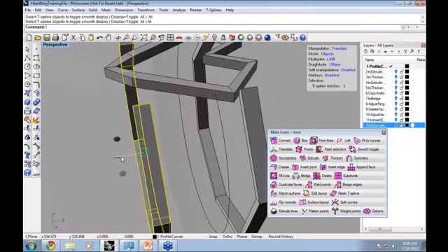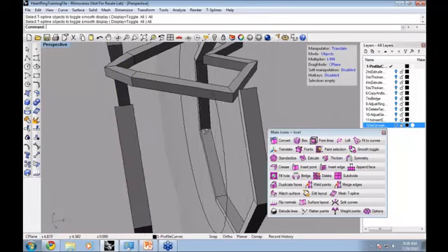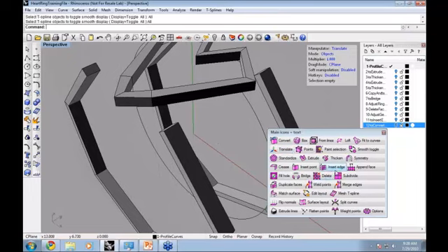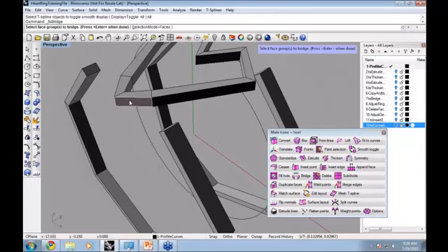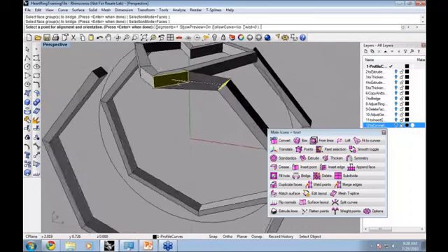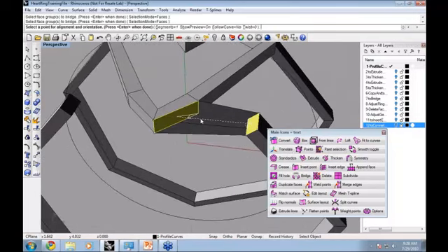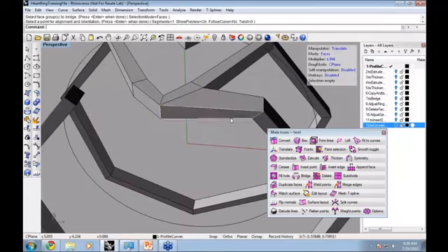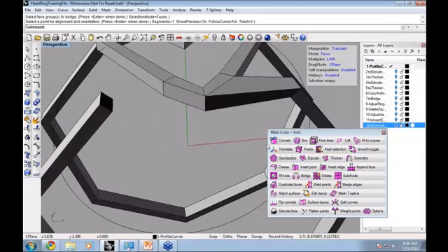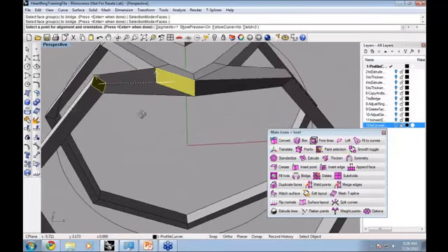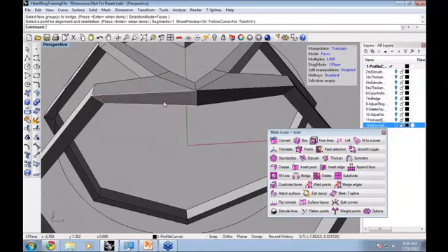So now that I can see this, I'll move this a little bit so that it's lining up better with the faces. And go ahead and use that bridge command. So just like we did previously, with the bridge command we select one group of faces and another group of faces, and make sure these arrows are lined up and in the right corners. Let's have one segment, and just hit enter. And we'll do that again here. So run the bridge command. Select this face, and again, those are wound the right way, so I'll hit enter.